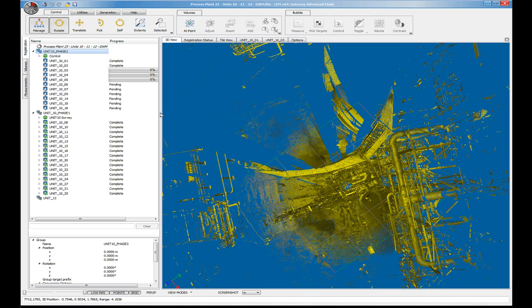As Ryan mentioned, there are two new time-saving features within LFM Server 4.2. The first is multi-threaded scan conversion, which, as we can see here, allows us to convert more than one scan at a time. The number of simultaneous conversions is based on the number of cores available on the machine minus 1. So in this example, we have a 4-core machine, and so we're converting 3 scans at once.